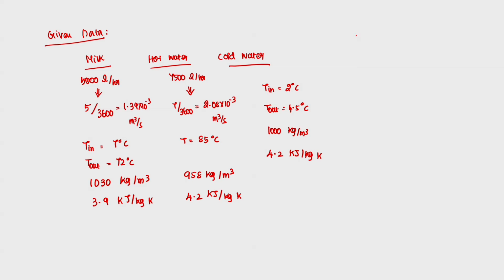And if we remember, we just have seen there are three major sections: heating, regeneration and cooling. In the regeneration section, the pasteurized milk which comes out of the holding tube is used to preheat the raw milk. That is nothing but the regeneration section. So, what information is given for all three sections, we will just see. This is the heating section, another is the cooling section.